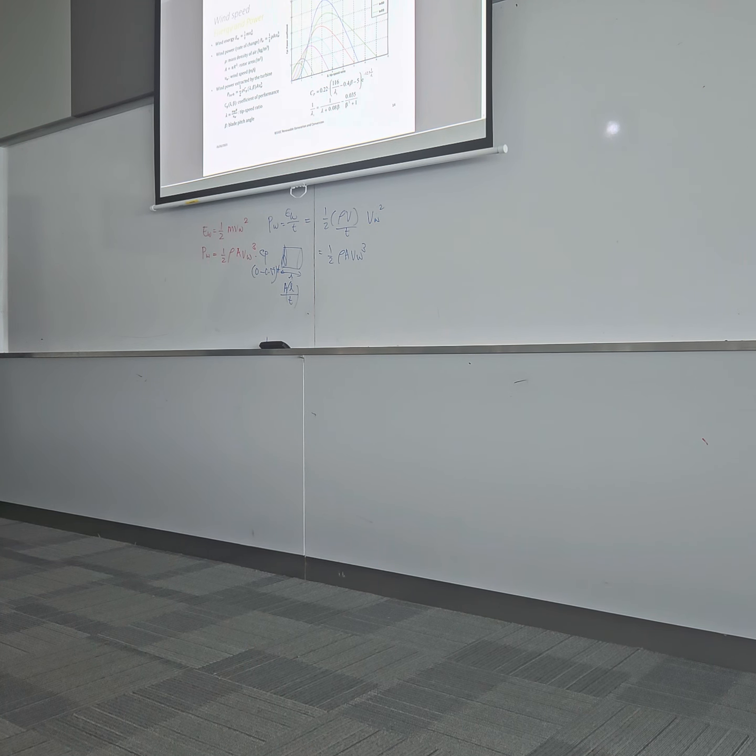Okay, so as you change the blade pitch angle to the green one, 2.5 degrees, that decreases, but perhaps in the higher tip speed ratio, you will have a higher coefficient of performance there. Okay, so in other areas as well, maybe in this range, a low tip speed ratio, others perform better than the blue. Okay, but for most of the ranges, blue is the best one, so you can determine from this.